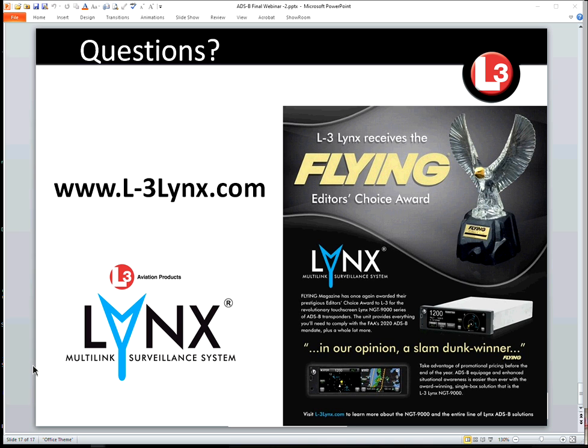Ghosting can be a problem with just RF technology, antenna locations. There's a lot of different variables to why you might receive ghosting. It could even bounce off runway environments. It's an anomaly that happens with a lot of other devices. The L-3 devices, I have seen ghosting in the past, but I fly these things hundreds of hours a year, and I don't usually see ghosting at all.